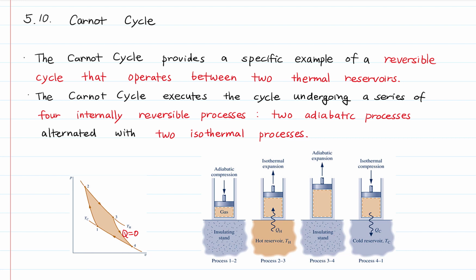The specific volume increases from V3 to V4. As there is no heat addition to the gas, the internal energy of the gas decreases. The temperature of the system drops from TH to TC.